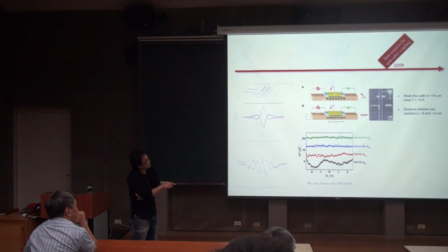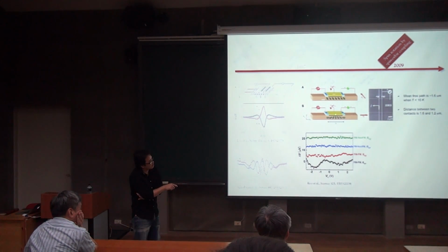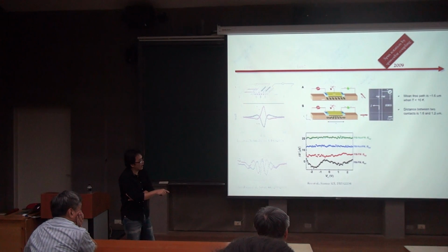If you change it to the X direction, so it is not parallel to the Y direction, the electron injected is along X and can start to rotate around Y. When you go to anti-parallel, there's no current. When you go to parallel again, you have current. By changing the gate voltage, you change the electric field, and you also change the spin precession frequency, which gives you this kind of pattern: parallel, anti-parallel, parallel, anti-parallel, parallel, anti-parallel.